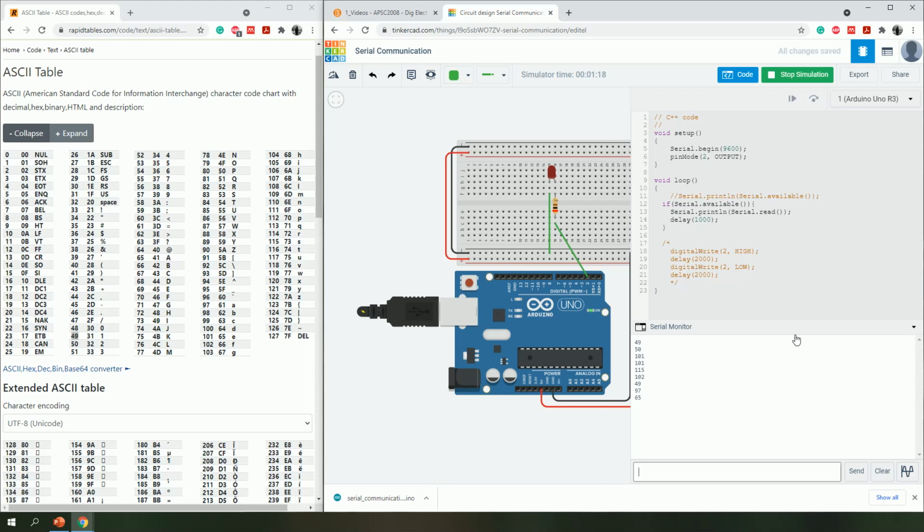So this is what happens. When you use serial communication, it communicates in ASCII. It doesn't use the normal communication. So if I wanted to check a condition and print accordingly, I could say I can send 1 and check whether it is 49, and I can do it like that.